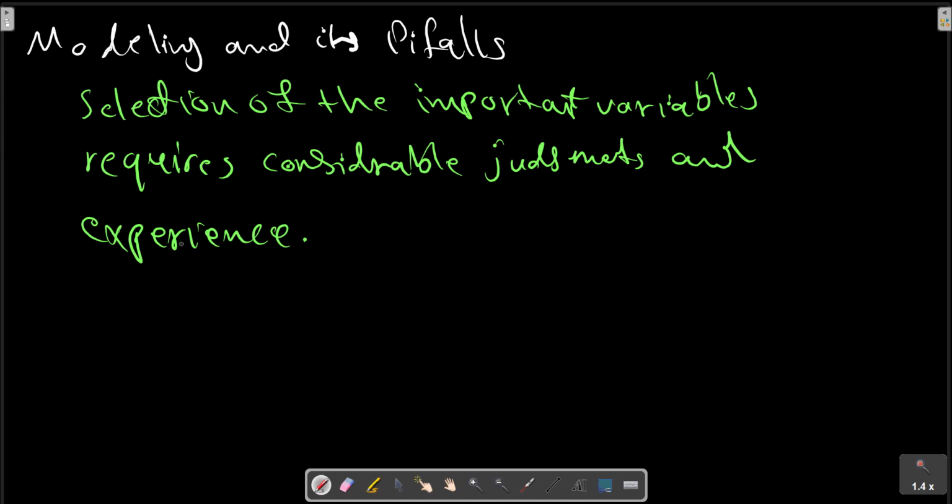The engineer must decide, for example, whether viscosity can be neglected. Are there significant temperature effects? Is surface tension important? What about wall roughness? Each pi group that is retained increases the expense and effort required. Judgment in selecting variables will come through practice and maturity. This course should provide some of the necessary experience.